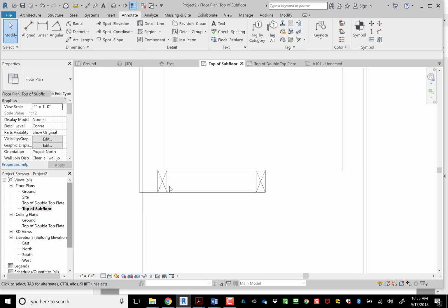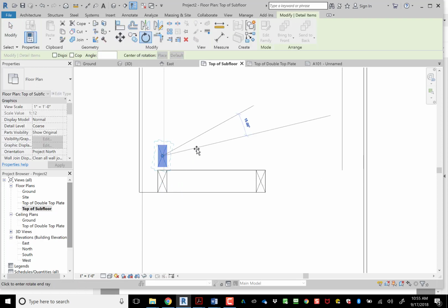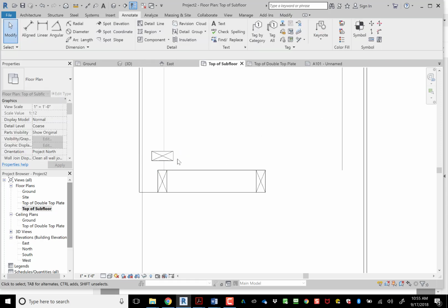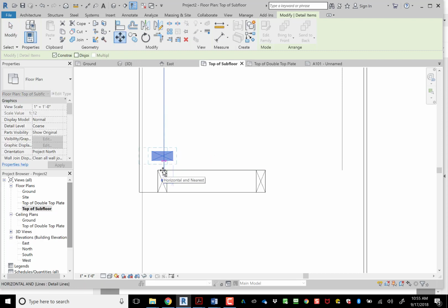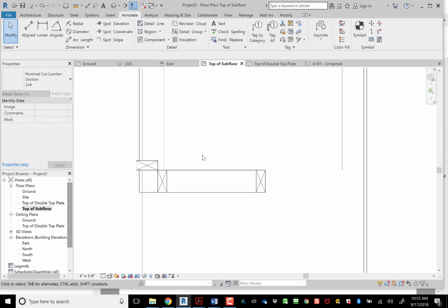So this is what I was saying earlier. When you start to lay out the framing, I'm just copying and rotating. So rotate is RO, copy is CC. Move, I don't even know, so I just do it manually. To snap to something, you do SE for endpoint. You notice that it won't go there, so you uncheck constrain, and then it will go diagonally.